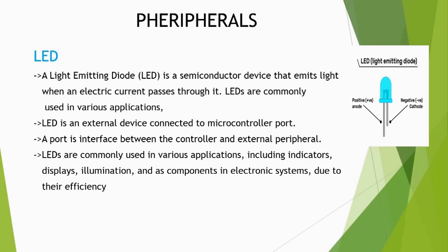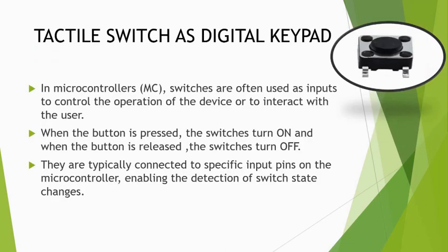tactile switch as digital keypad. In microcontrollers, switches are often used as inputs to control the operation of the device or to interact with the user. When the button is pressed, the switch turns on, and when the switch is released, the switch turns off. They are typically connected to specific input pins on the microcontroller, enabling the detection of switch states.